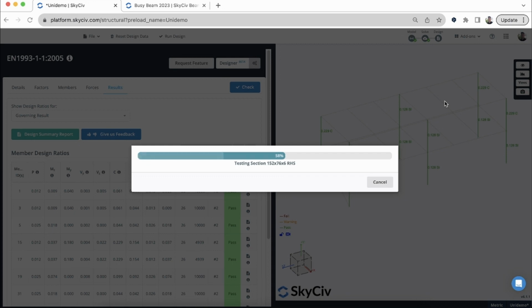The only real result that this typically has a large effect on is the deflection limit. If you can imagine, you load really heavy sections to begin with, the deflection limit might fail, and if you have the interval set to 0, no matter what section you use, it's always going to fail that criteria. So that's why it is important to select something that is more or less close to something you would choose initially. Then you're going to get more accurate deflection results being used within the designer.